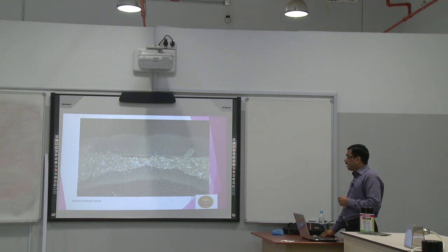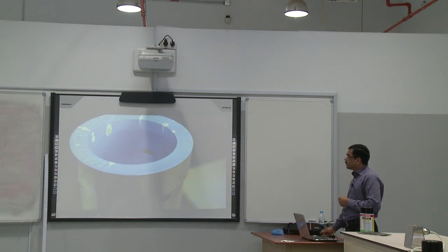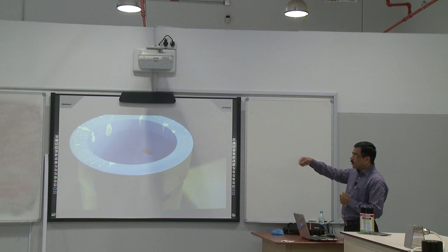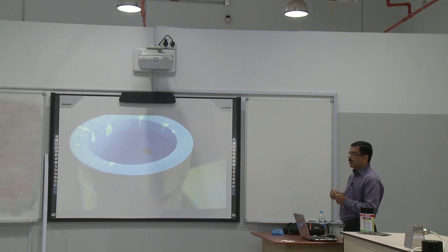Like this, incomplete fusion. This is not completely welded. Some indications like this, fluorescent indications we are getting. This is an indication from the fluorescent type 1 penetrant.